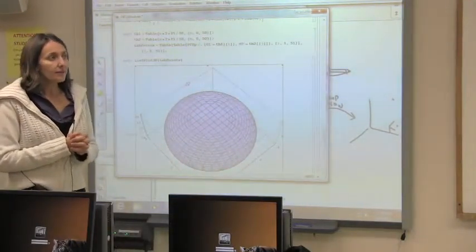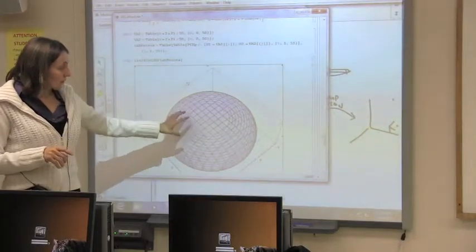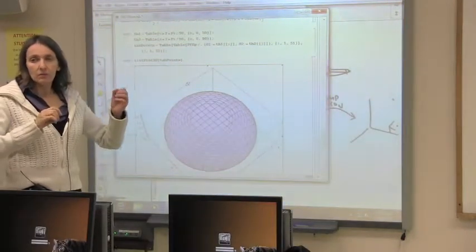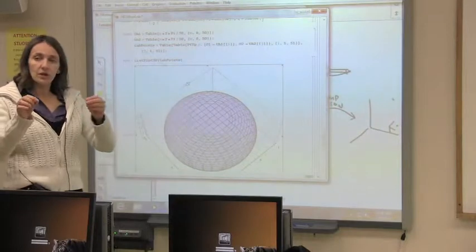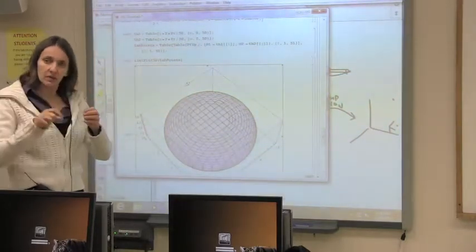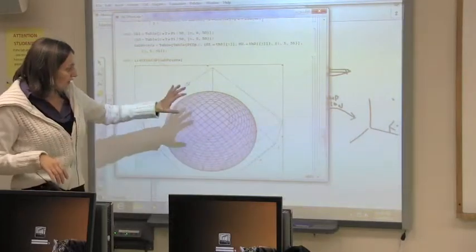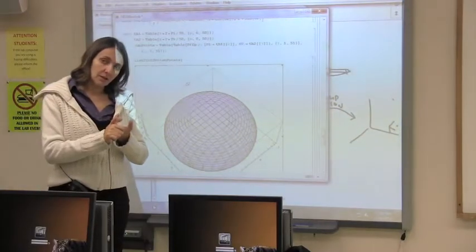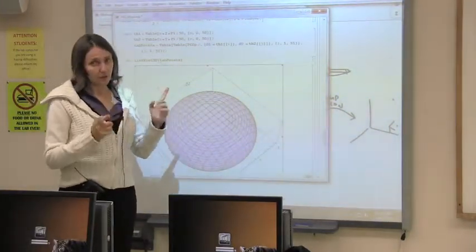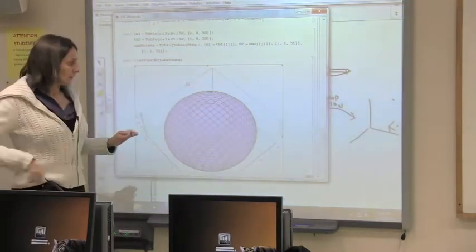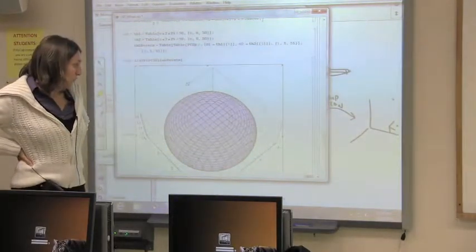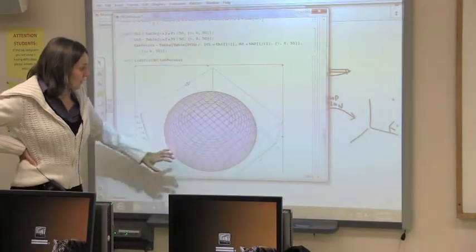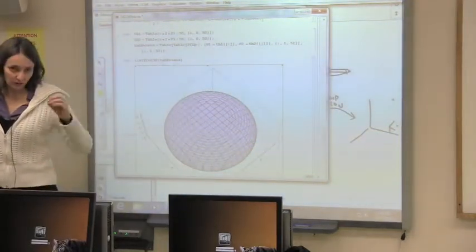Okay, singularities do not appear in the position workspace. So whatever positions you can reach, despite whether it can move or not, it doesn't tell you how smoothly you can move from one to the other. That's when you can run into a singularity, on singular points. So that is not identifying the position workspace. Then you have to look at the velocities, and you can look at that through the geometry, but it's like a smoothness problem basically. So one obvious singularity is the boundary, and that you can get from here, but not the internal singularities.